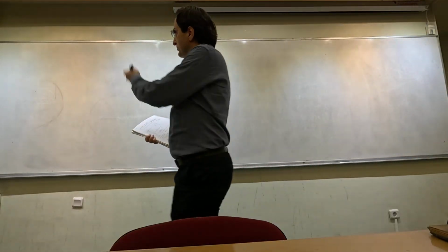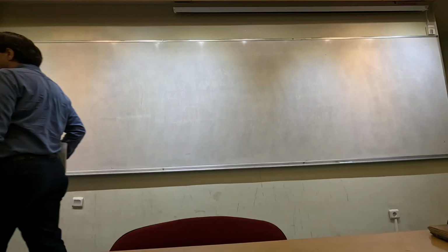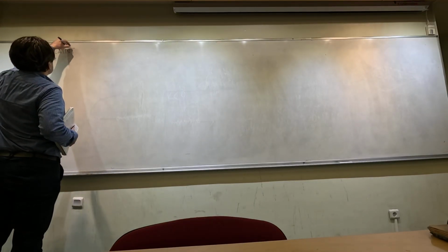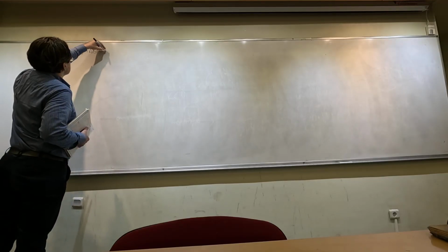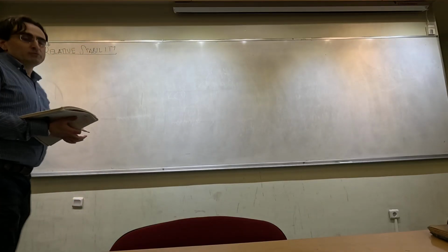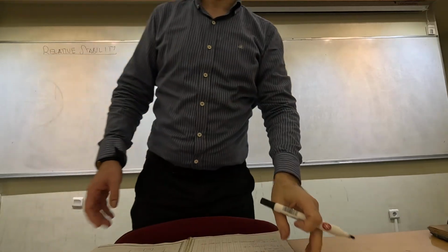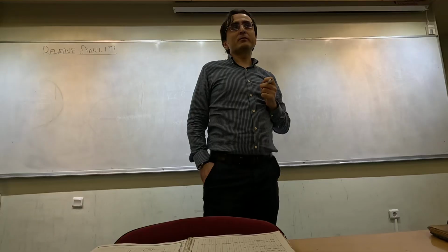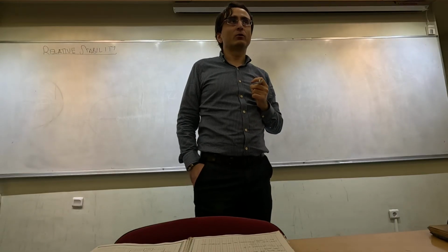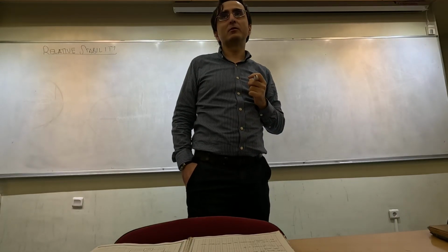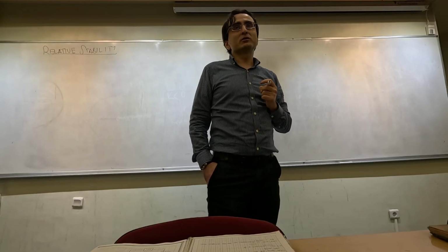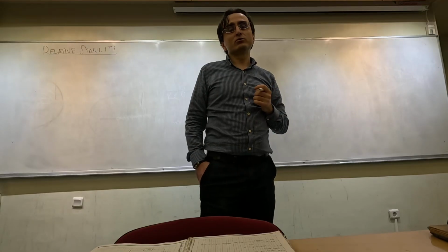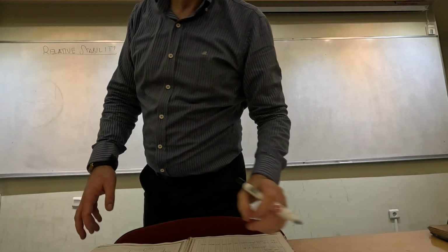So the concept that is going to take us to the concept of Bode plots is going to be the concept of relative stability. We are first going to learn some performance measures in terms of the frequency domain quantities. So these performance measures will be something that you might have seen before. They are going to be called gain margin and the phase margin of a system. So these are going to be the performance measures of the system or controllers that we are going to design using frequency domain quantities or the Bode plots.